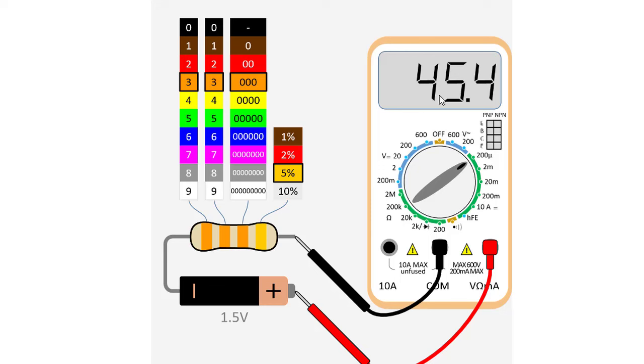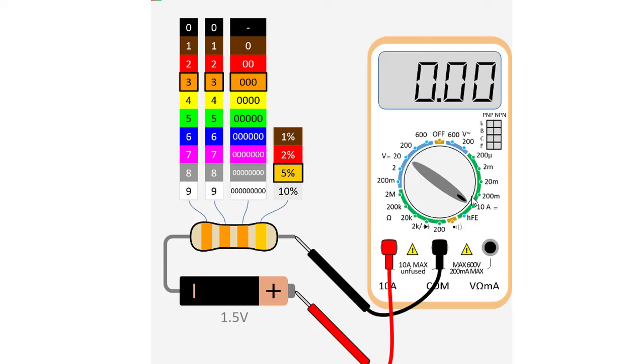So here we are getting 45.4 microampere current. Then next, if we want to measure a larger current, that time we have to change the knob and change this probe from here to here. This is for measurement of 10 ampere DC current.